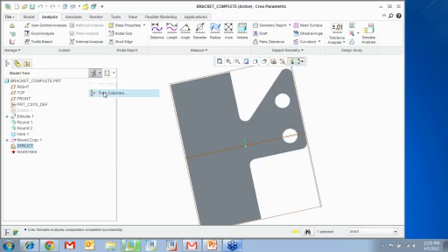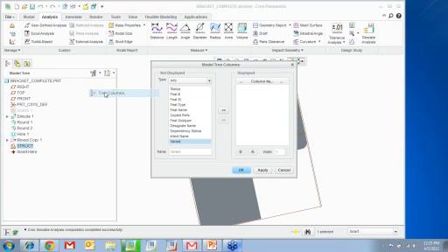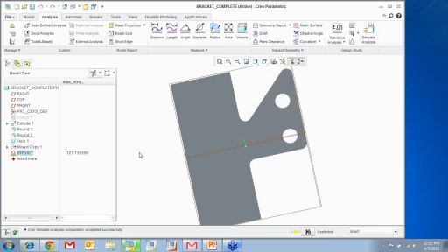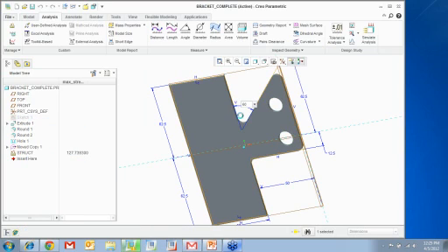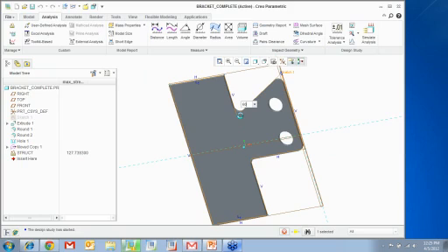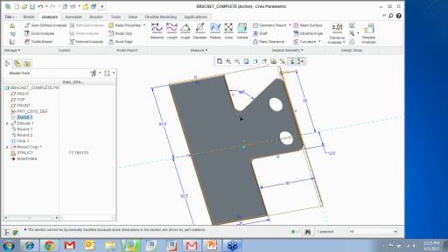So what is the von Mises stress? So go to 3 columns, feature parameters, add that, and that's the value of von Mises stress. So now if I edit and change that value to 60, you can see my von Mises stress changes.